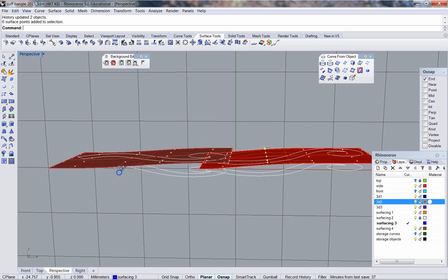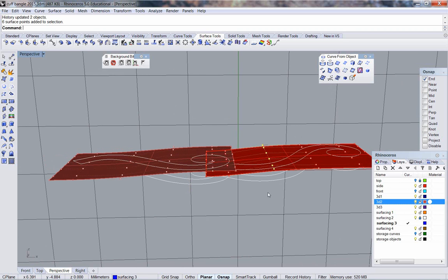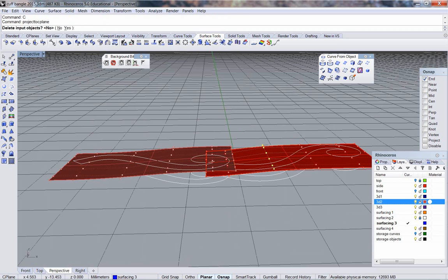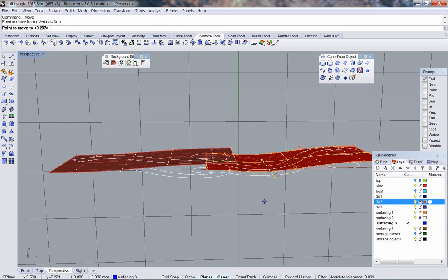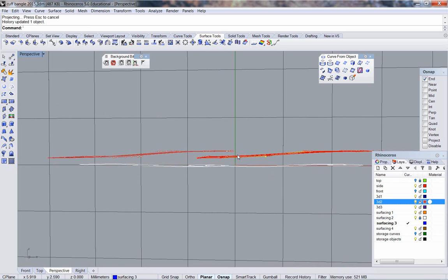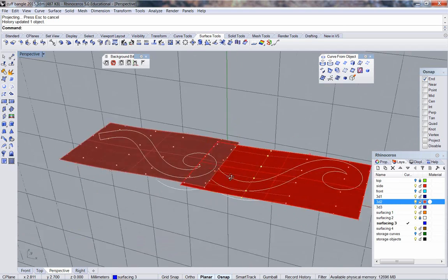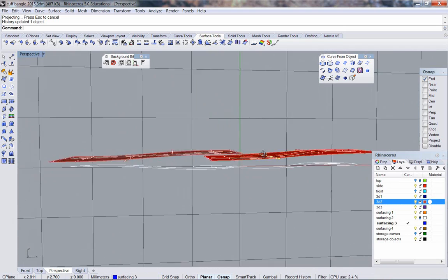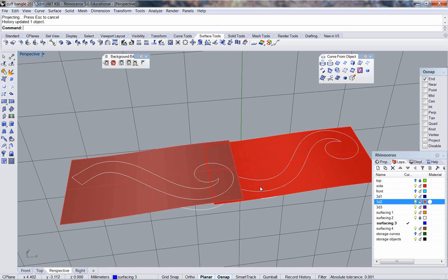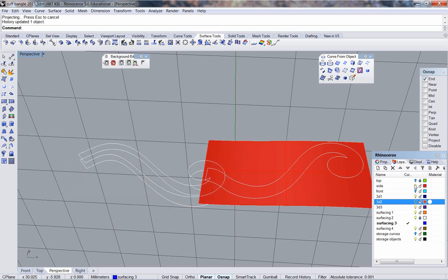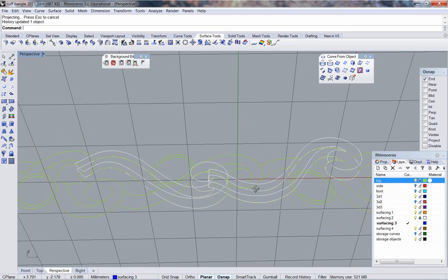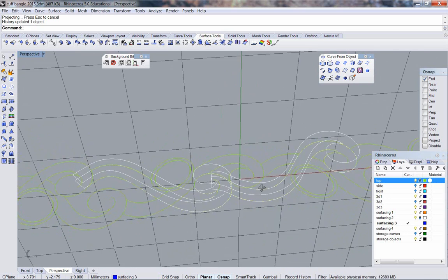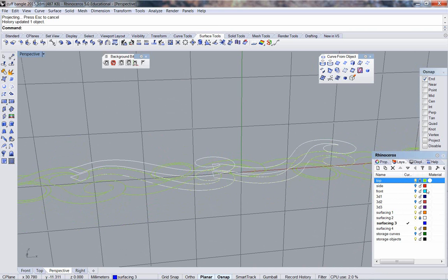This was actually set to the same as this was 2 millimeters over here. I'm going to do the same here. Project to C-plane, delete input, yes. Vertical C-plane, enter, click to enter. So that these 2 are doing about the same thing. That's pretty nice. Take a look at my drawing again. That should work. Let's see if it does.